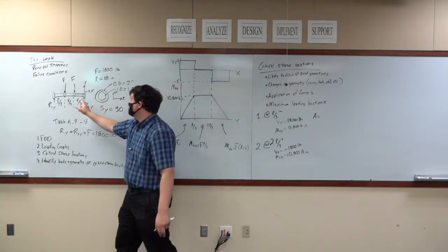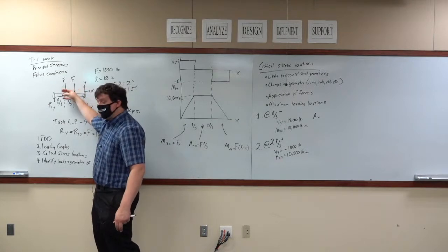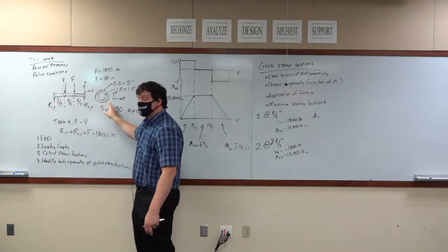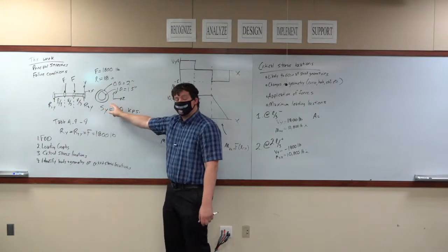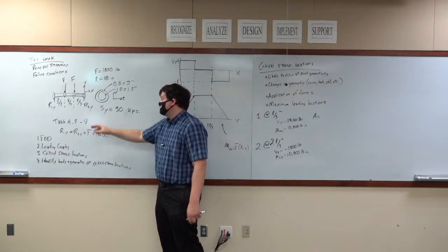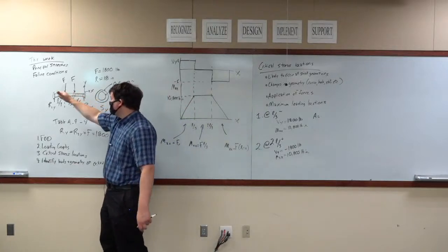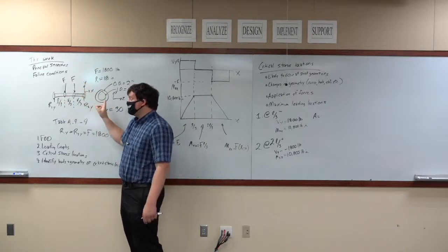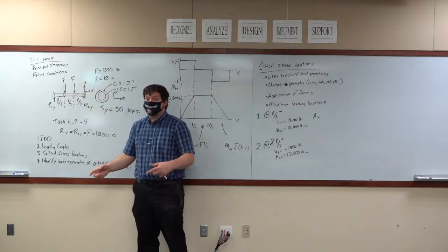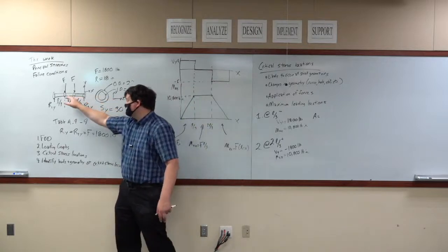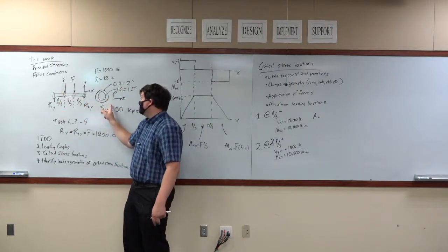It is the cross-section. The load is being carried inside of the beam, along the beam. So this is what's carrying the load. This is what you care about as far as area and inertial properties. Now that said, if we had a z-directional load here, your area wouldn't be this one anymore because it would be carrying a load in a different direction. But because we're carrying these loads across that cross-section, it has to be this one.